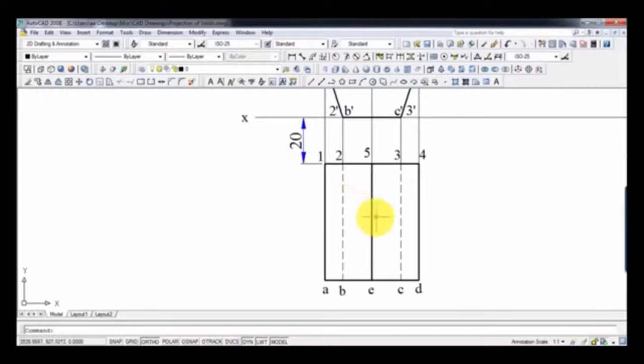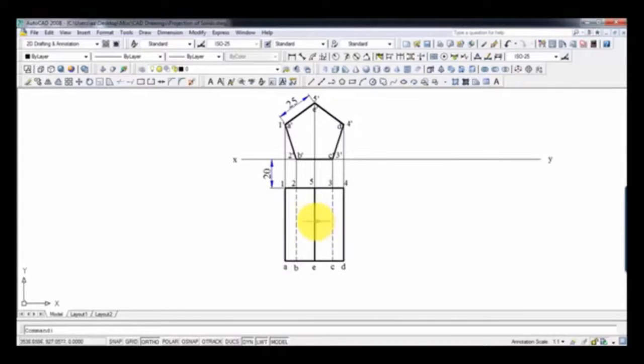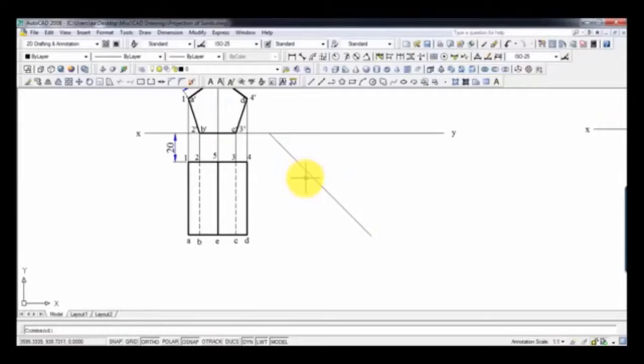Now let's head over to step number 2, where we are going to incline this. Keep this top view at an angle of 45 degrees. That's exactly how this pentagon is going to be kept. This edge over here, it would appear from the top view that this edge is making a certain angle with the vertical plane, and that is in fact, I guess, 45 degrees. If the axis makes a certain angle, then all these edges are going to make the same angle with the vertical plane.